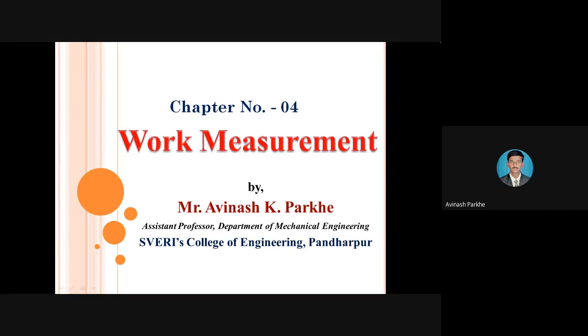That means the first 3 operations I have performed for 10 minutes each, so the total time is 10 plus 10 plus 10, 30. And the last operation I have performed for 5 minutes. That means a total of 35 minutes of operations. At the end, I can say that the total 4 operations on that job are taking near about 35 minutes. That means 35 minutes is my standard time to convert that raw material into the finished goods. So that concept, the time measuring for each and every operation, is called work measurement.